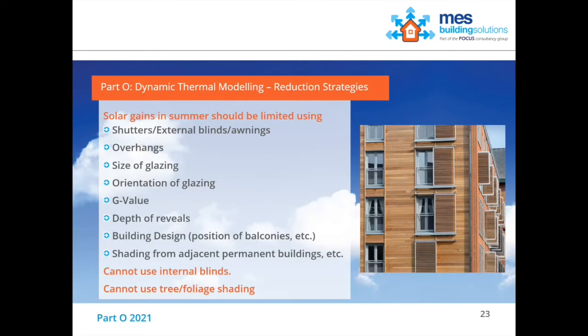What this approach allows us to do is consider every single aspect of the building design. So we're not just asking, this has got X area of glass, is that greater than the threshold? Can we open the windows? We can shade those windows using any form of shading we like, whether that's a dynamic approach, i.e. something which automatically opens and closes, or a blind that automatically drops if the sunlight exceeds a certain threshold on a sensor. We can look at overhangs.